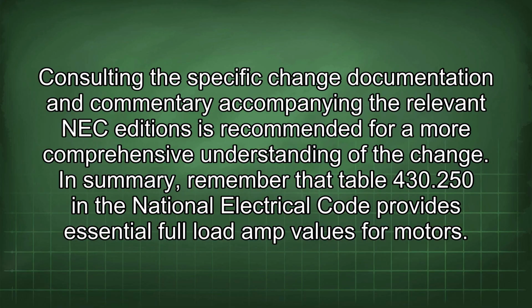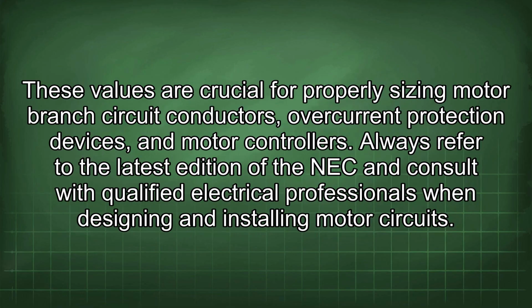Consulting the specific change documentation and commentary accompanying the relevant NEC editions is recommended for a more comprehensive understanding of the change. In summary, remember that Table 430.250 in the National Electrical Code provides essential full load amp values for motors. These values are crucial for properly sizing motor branch circuit conductors, overcurrent protection devices, and motor controllers.